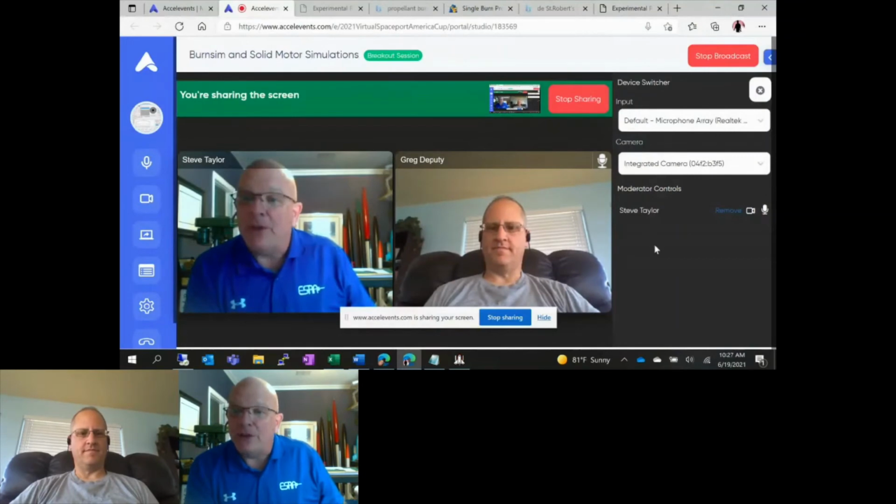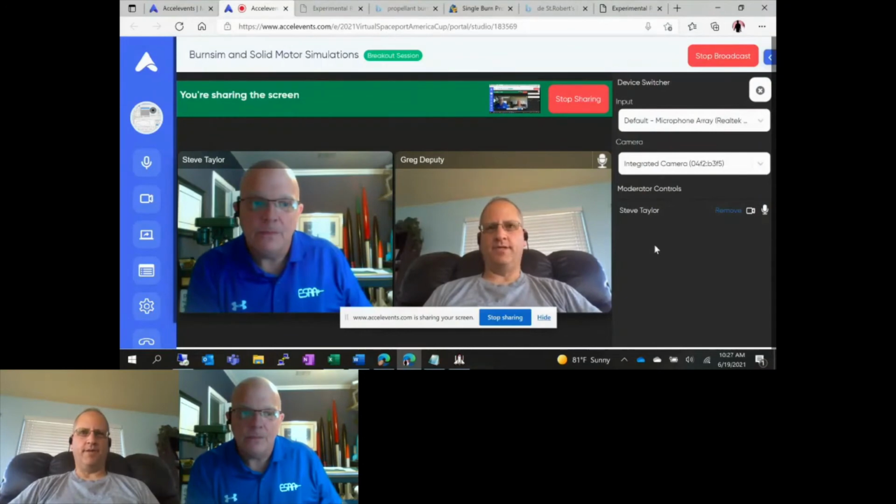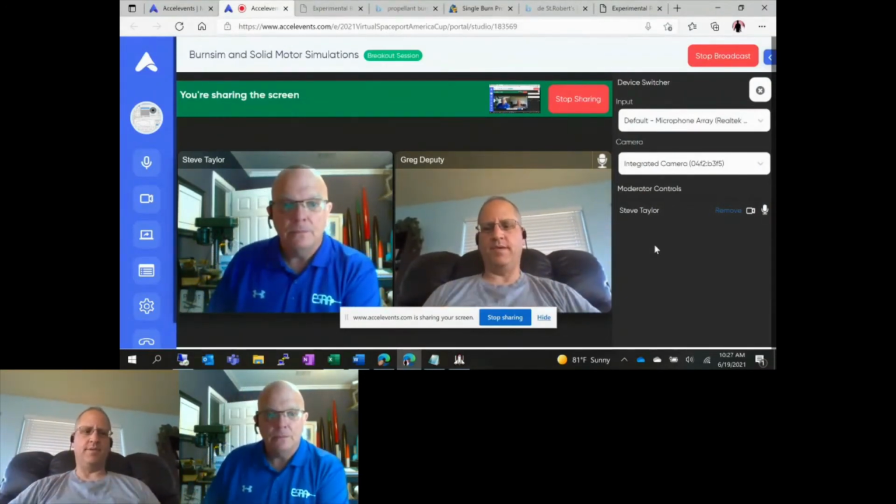If we can use other geometries, I assume we would use average pressure to determine the burn rate. So that brings me to wonder what an appropriate cutoff would be to give an accurate result. Yeah, the devil's in the details on this stuff, absolutely. And like I mentioned, when you're using an end burner configuration, they get big and it gets hard to light that surface evenly to get a clean burn, that kind of thing.